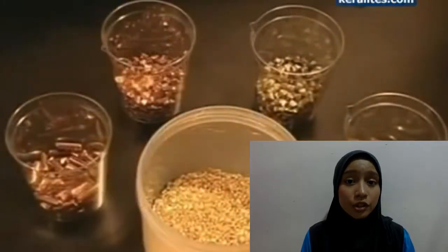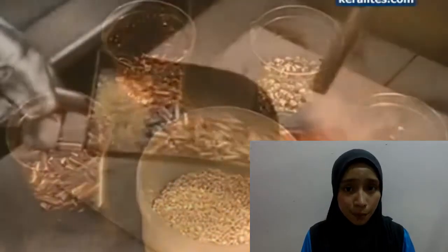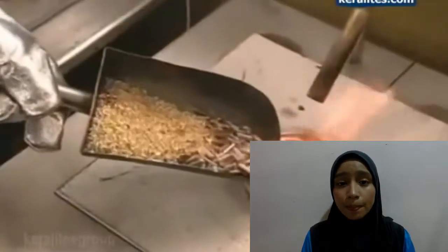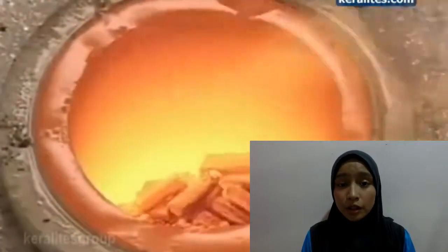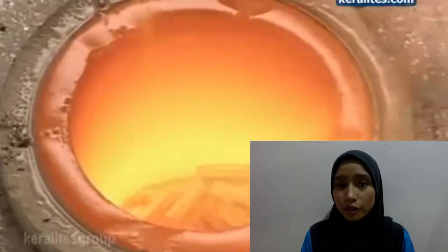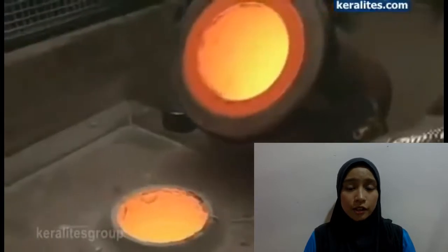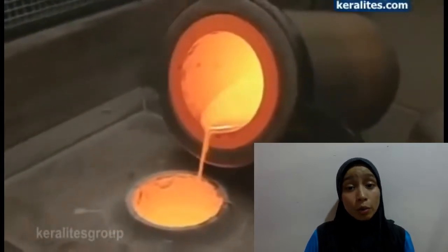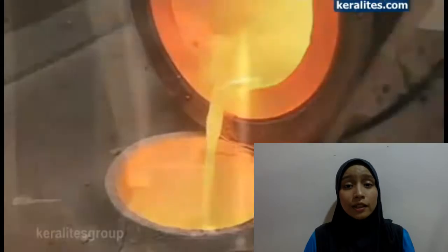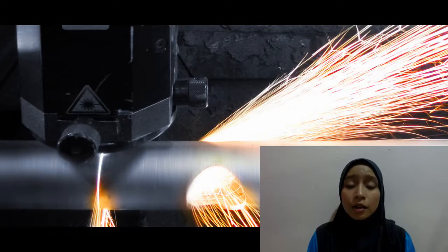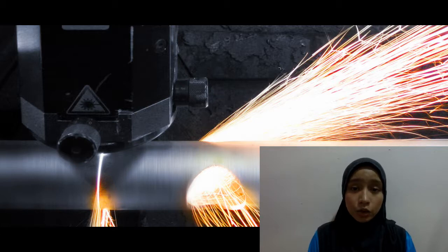In order to produce a chain necklace, the first process is the melting process, where all the mixed raw material is melted at more than 1000 degrees Celsius. Next is the casting process. Casting process is about forming a rod from the molten metal by using a casting machine. Then the formed rod will go to the cutting process and it will be cut in half by a laser cutting machine because it will be easy to handle for further process.